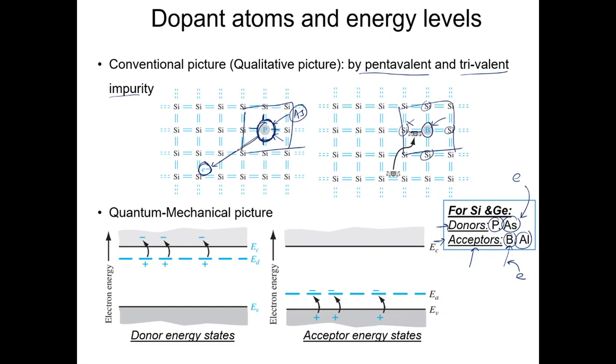The band would actually experience another energy state being introduced below the conduction band if it is phosphorus, and if it is boron, it would notice another energy state introduced just above the valence band. Now this energy state will have a finite probability of occupying electrons. This energy state above the valence band will have a finite probability of capturing electrons.